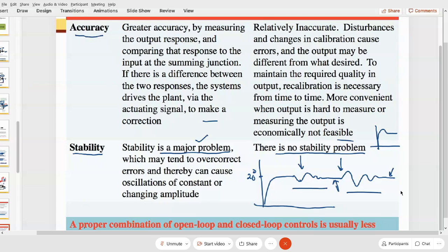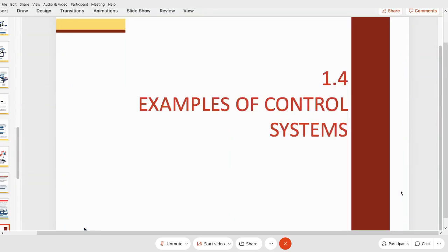After that, the spinning process and draining process are all open loop control systems. But controlling the level of the water is a closed loop process. So one system may be a combination of a few methods, maybe open loop, maybe closed loop. We combine them to become one complete process. Okay, so it can be done, open loop or closed loop.